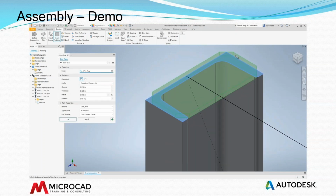So when I do that, it gives me a preview of the end cap that will be placed on this channel. I can specify the chamfer distance, the thickness of the plate, and an offset if I needed to. But again, I want clearance for some welding. So I can do chamfer corners, I can do utility corners. In this particular case, I'll keep it as the chamfer. 1/8 of an inch is fine, and I'll place that end cap right there.